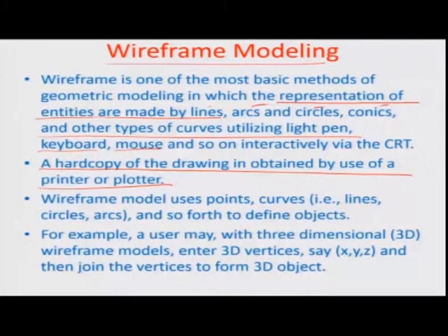As I have told you earlier, the wireframe model uses some basic geometries like points, curves, lines, circles, arcs, and so on to define various regular objects. When it comes to slightly irregular or complex objects which are of more appropriate engineering interest, you need to use another concept of synthetic curves, as I am going to point out later.